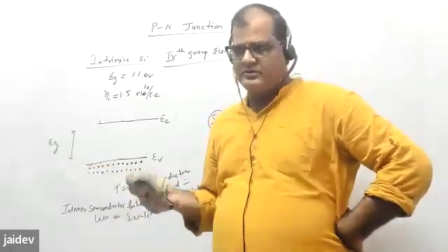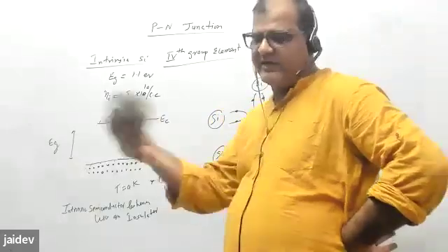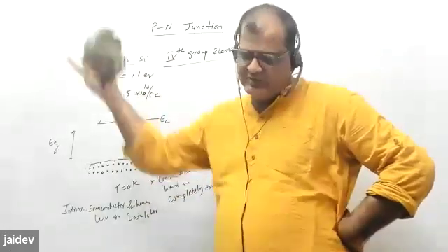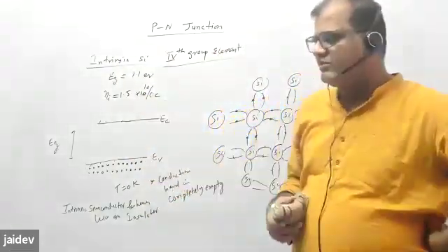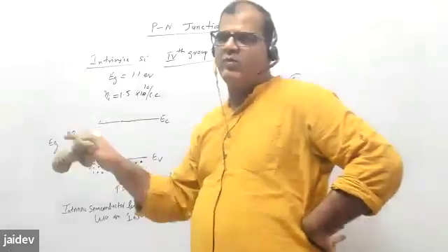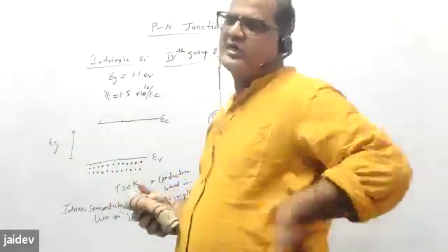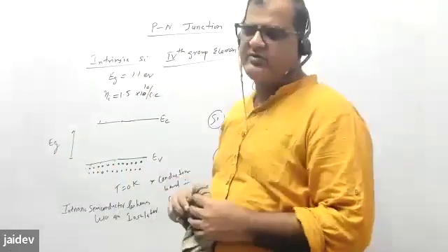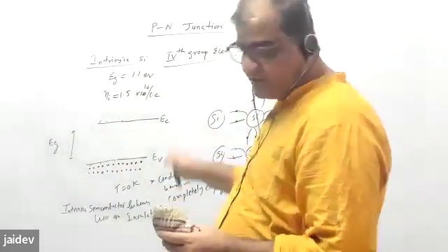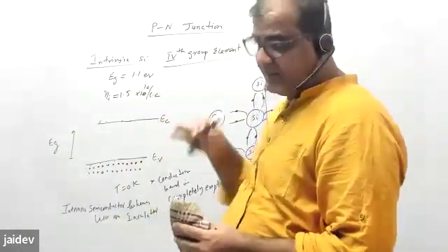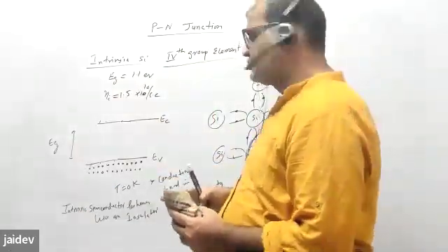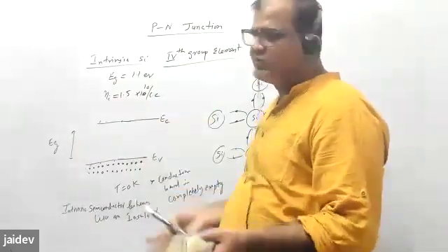Something like 5 or 10, not 5 to 10 Kelvin, but 5 degree centigrade, 10 degree centigrade. That is not that low. If you go lower, you require some special modification of the materials. But in the working range where human beings operate devices, these types of semiconductors are not useful because their conductivity is almost zero. At T equal to 0 it is 0. At the operating temperature, say 300 Kelvin, you have some conductivity, but that is also not useful.